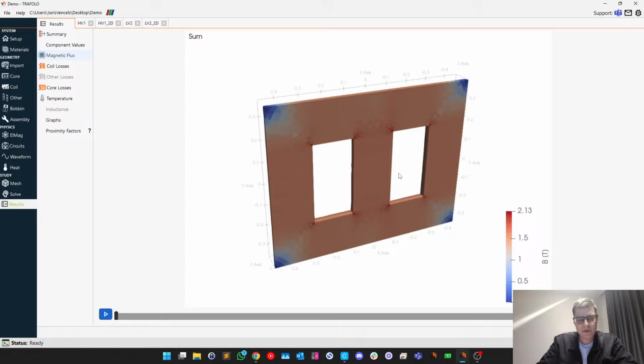Many of you will likely ask, how about anisotropic permeability or anisotropic BH curve? Unfortunately, no. Currently, it's uniform. We do not provide yet ways for you to set anisotropic permeability or BH curve, but we are considering adding it in the future. So if there's interest, let us know. We might think about workarounds to allow you to do those simulations, but we would expect that you then help us to validate those models too.